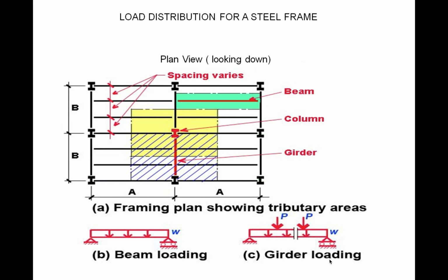So when it arrives, you know what piece it is and where it needs to go. All right, so just simple concepts for steel. It all goes off of beam design. Basically, the idea here is that load gets distributed through those beam members into the column. So the beams take a distributed load, and then they go from those distributed loads on top to specific point loads that are through the beams, and then into your supports or your foundation.